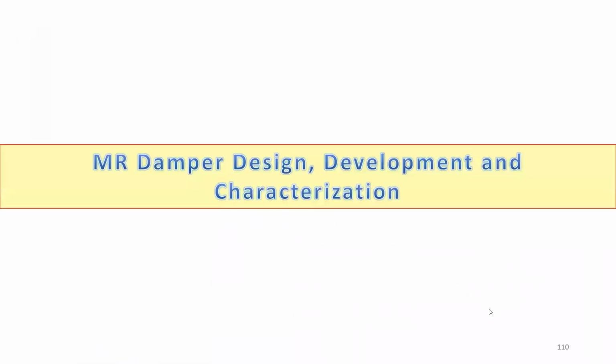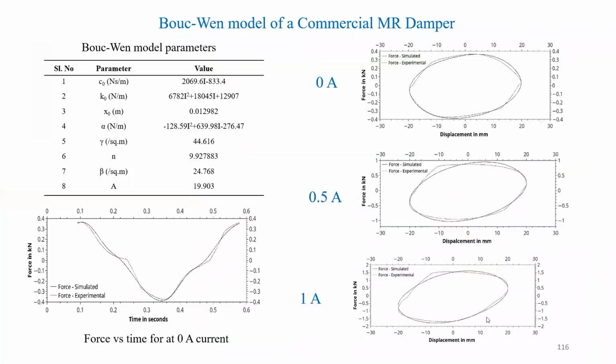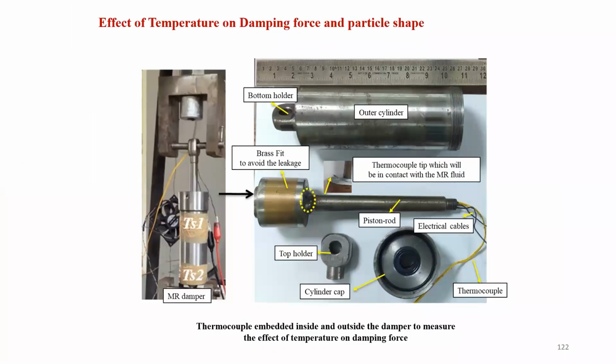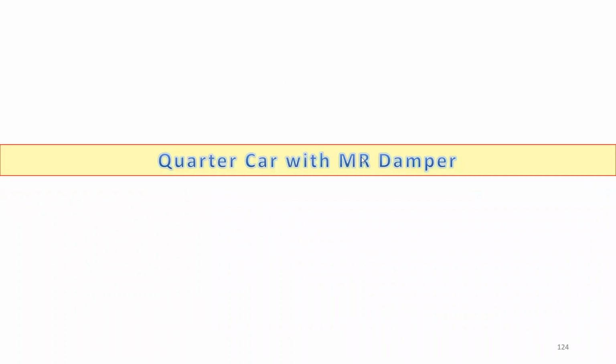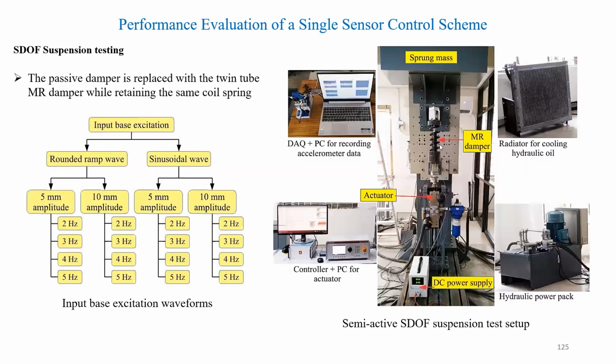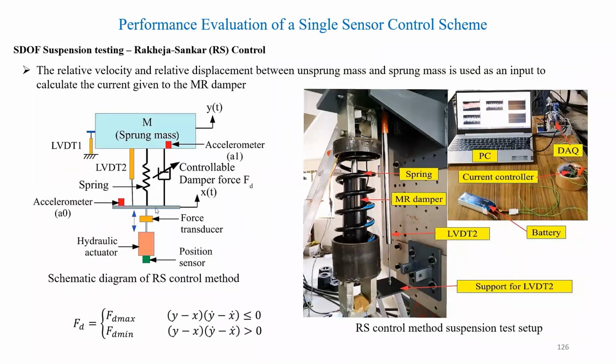So that is what is done there. So that model, the quarter model, half model, these are all available. This vibration analysis, if you are interested, is available. The quarter car model is available in Introduction to Mechanical Vibration by S.S. Rao. All these solutions are available, and you have to make this model and test it and prove it for different amplitudes and different frequencies. Then see what the behavior of the damper is. That is the same as what I explained earlier.